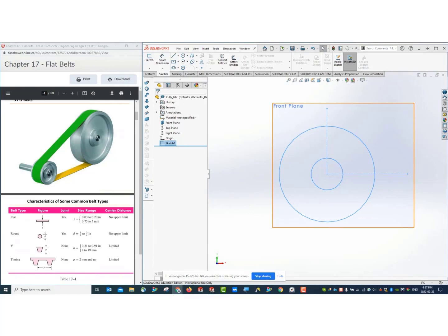The center, and you have this degree. You should have a taper angle. So when the belt moves to this side, because of this taper, it will be self-centered. We are not going to include those details here.